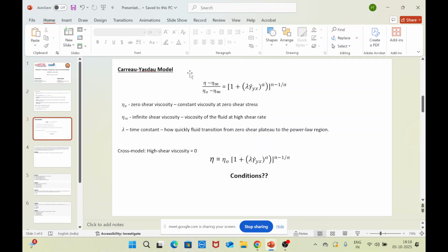For any polymeric system that contains nanofillers forming a network structure, because of the presence of the crosslinks, what usually happens is that for a very low applied stress, these crosslinks will not break. So there will not be any flow. This holds up to a certain stress, called the yield stress. Once the applied stress exceeds the yield stress, there will be a steady flow in these polymer systems. Till then, there is no flow, and the polymer system exhibits more of a solid-like behavior.